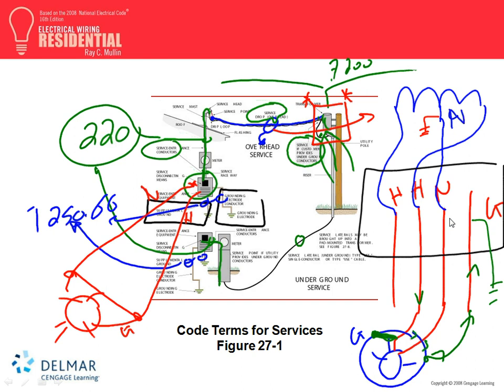So to facilitate the trip of the circuit breaker, what they do is they grab the hot and the neutral right here, and they bond them. Now, Brad, that current that could have, would have, should have gone through Mother Earth, which some of it probably would, at high impedance to the transformer, now has a very low impedance, very smooth track to go back to where? Back to the source. You can't damage the transformers. Right, that's the $64,000 question.